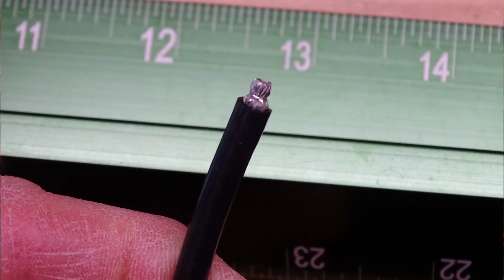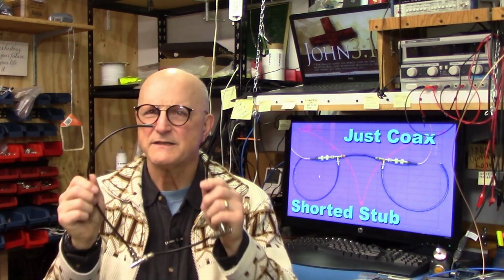The real difference in trimming this to tune as compared to the open stub is that we have to solder the short at the end of the stub every time we trim some off. Here's one important note. The tuning of the stubs does affect each other. Once we approach this target frequency, we want to be sure to trim them both in concert with one another. Now, how much do we take off at a time? Well, I'm going to trim off a mere 1/4 inch or 6.4 millimeters and see how much of a change I see. Then, based on that observation, I will decide on how much to trim at a time.